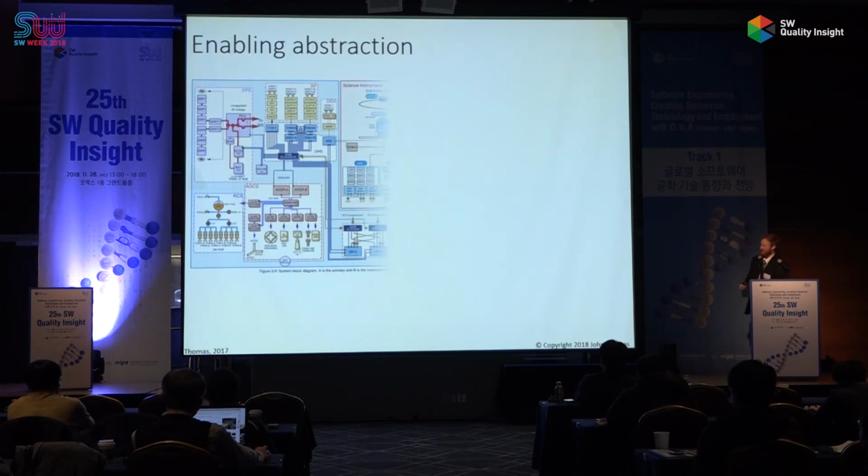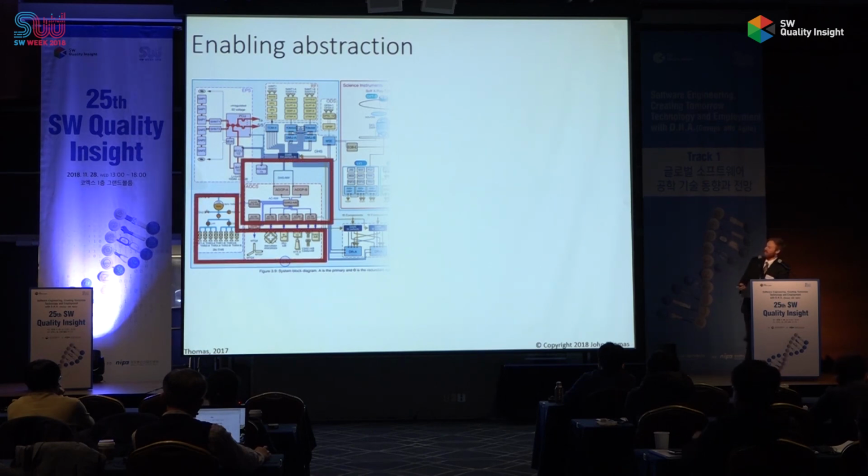Here's the logic behind a control structure. Do not start with something like this. This is too late. This is a detailed block diagram, or it could be a detailed flow chart. This is too late. You need to start before you've built the software. You need to recognize, if you do start late, that we can group these things together. How do we group them together? There are many different ways, by function, by proximity, by connections, and so on. In STPA, we group them by control.